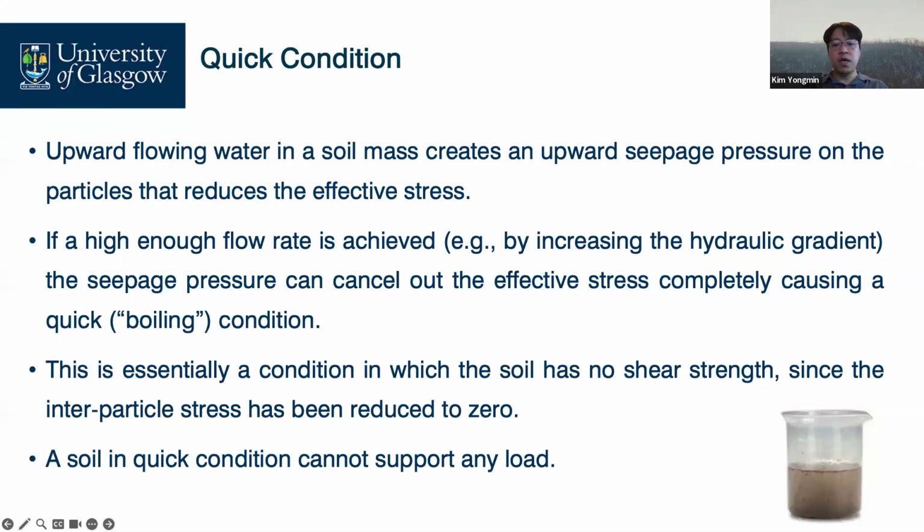This shows how the soil loses its shear strength since the interparticle stress was reduced to zero. So in a quick condition, the soil particles behave as if they are suspended in water, like they are swimming. The soil particles swim individually in muddy water. So the soil loses its strength and behaves more like a fluid than a solid. Can you imagine this water?